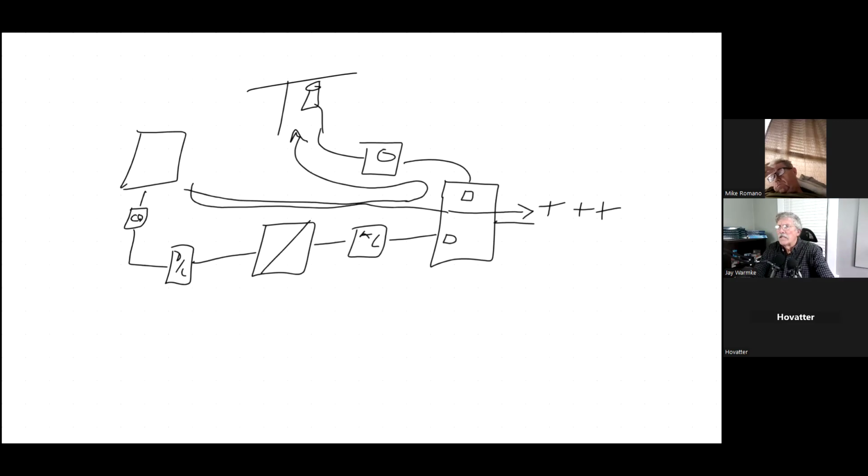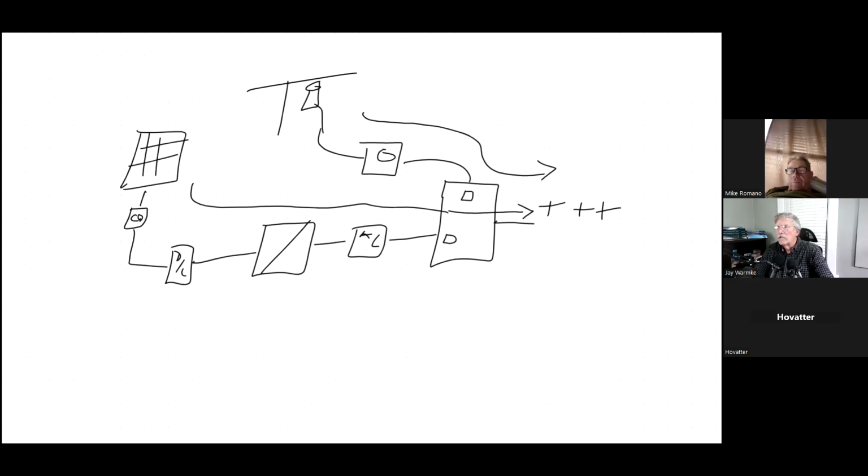What happens if I'm not generating enough power from my array? Well, all of the power I've got is going to go to the load, but I'm going to need to supplement that with power from the grid. So whatever's being generated from the array is still going through my inverter, but my loads are also going to be supplemented from the grid.